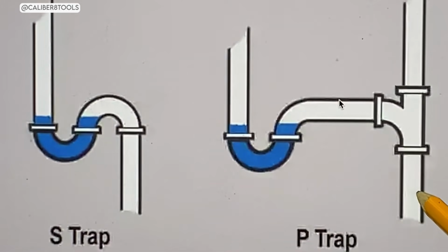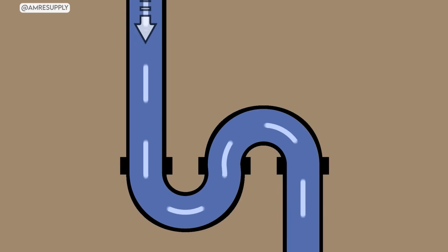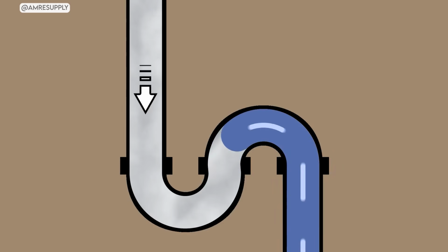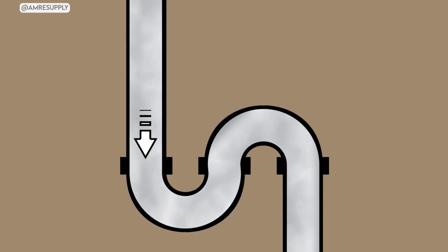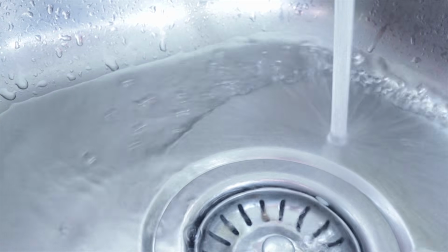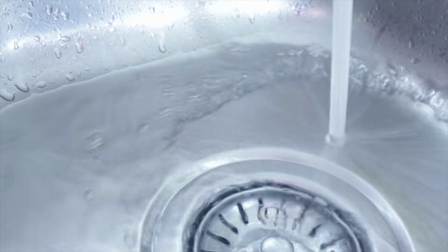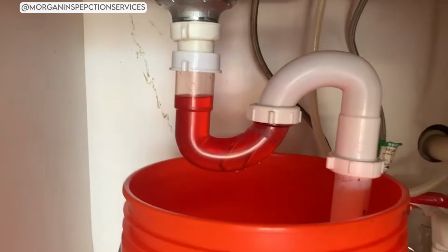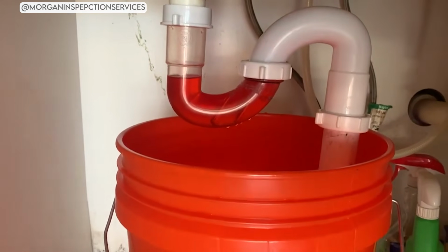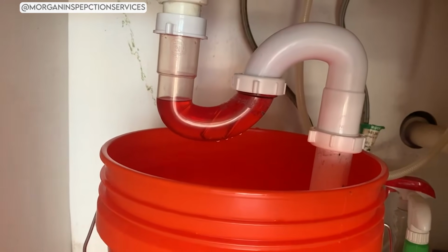This gentle flow helps replenish the trap seal without creating the heavy rush of water that triggers a full siphon. It is not a permanent fix, and it does not make the S-trap code compliant, but it dramatically reduces the chance of losing your trap seal between uses.